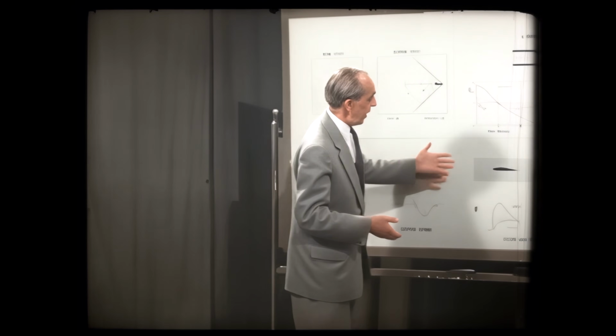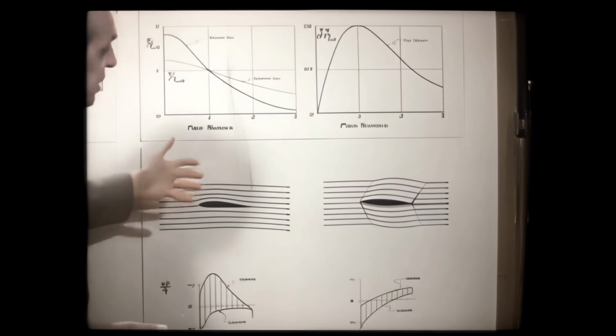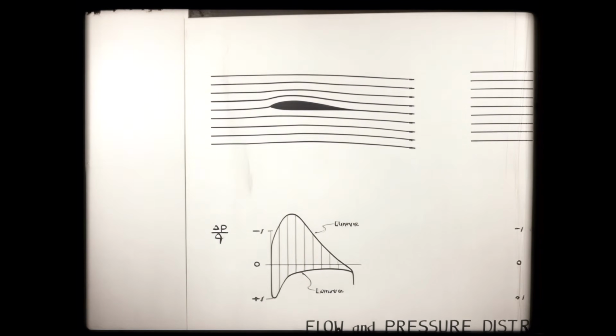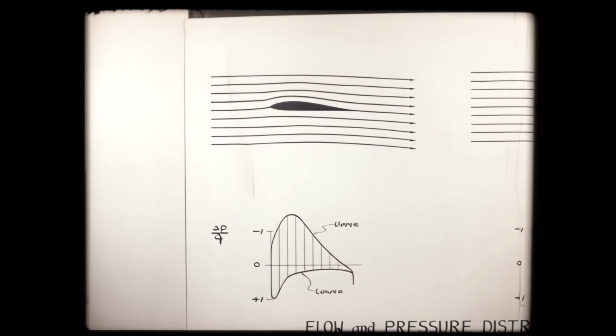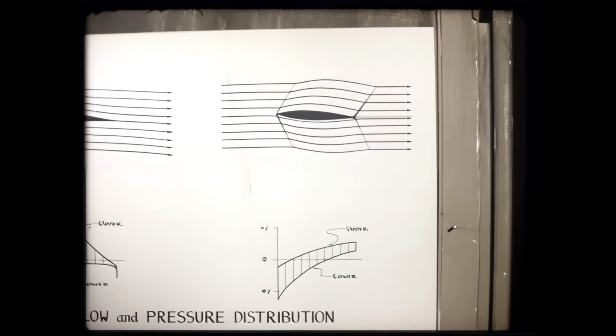On the other hand, as we see here, the pressure distribution on the wing also changes considerably, and we have a shift in the center of pressure, which was here at the first quarter of the airfoil, and here is almost at the center. This makes a stability problem in the supersonic range.